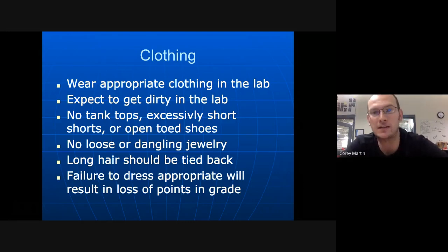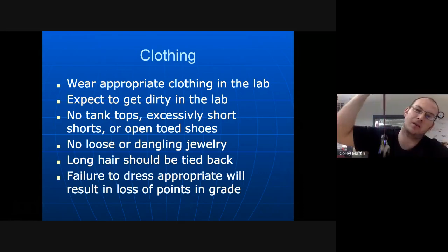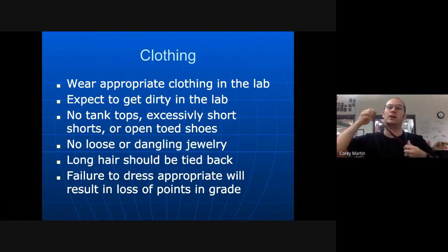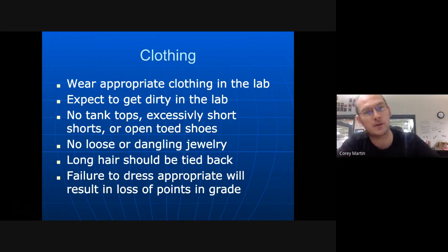No loose or dangling jewelry. So a lot of times I wear my keys on a lanyard, and I will take them off, or I'll wear a shirt with a pocket and tuck the keys in the pocket. Long hair, if you're a female especially, if it's past your shoulders, it really needs to be tied back in a ponytail to prevent it from getting tangled up in any kind of moving equipment.